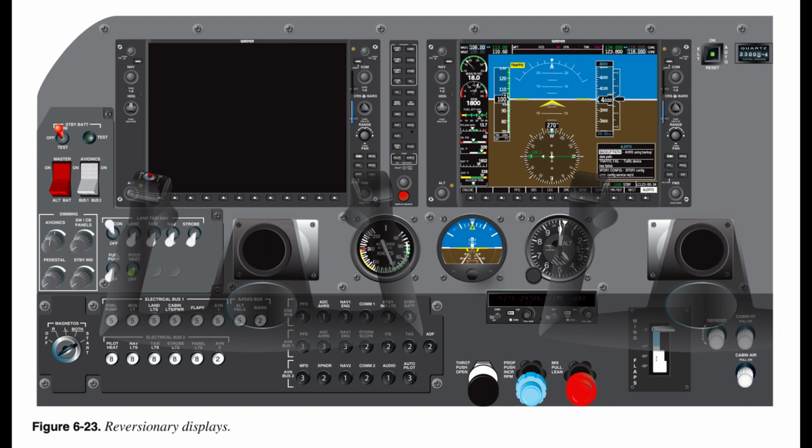Control and performance method. Aircraft performance is accomplished by controlling the aircraft attitude and power output. Aircraft attitude is the relationship of its longitudinal and lateral axes to the Earth's horizon. When flying in instrument flight conditions, the pilot controls the attitude of the aircraft by referencing the flight instruments and manipulating the power output of the engine to achieve the performance desired.